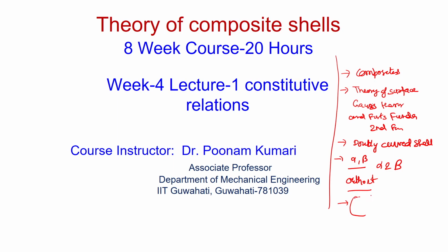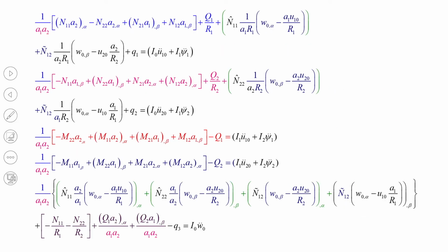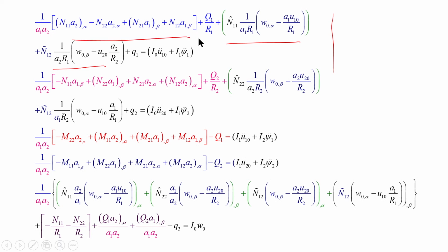In today's lecture I will discuss how to proceed further once we get the governing equations, and what the steps are so that we can get the solutions. Ultimately we are interested in the displacements, stresses and moments of the shell subjected to loading and boundary conditions. These are our basic governing equations of shell, in which we have taken the nonlinear terms as well as linear terms. We developed these 5 governing equations.